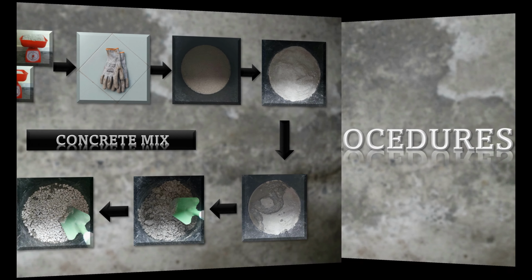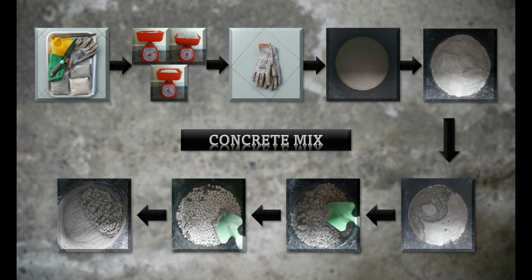Procedure. This is the procedure of preparing concrete mix for the control variable test. The mixing container and apparatuses are prepared by cleaning and drying before proceeding with the concrete mixing process. The quantity of materials to be used are prepared according to Appendix 1, Concrete Mix Design, for a trial mix volume of 0.00095 m3 by weighing each material using a weighing scale.